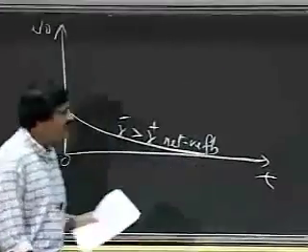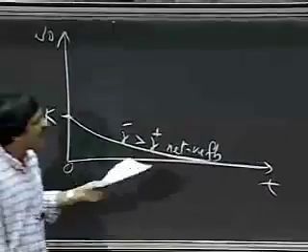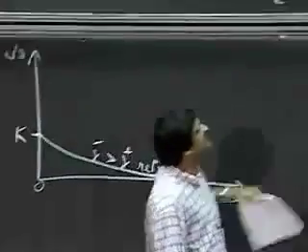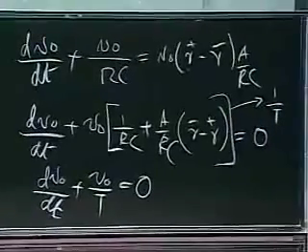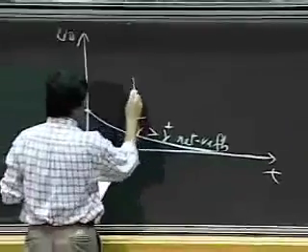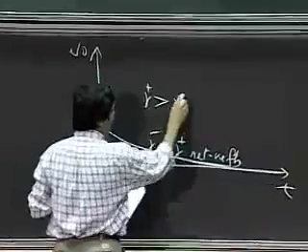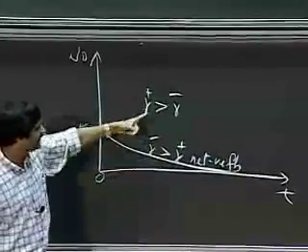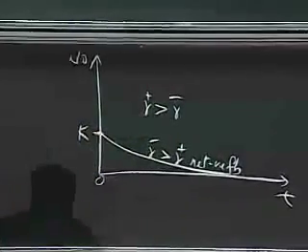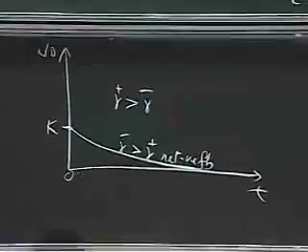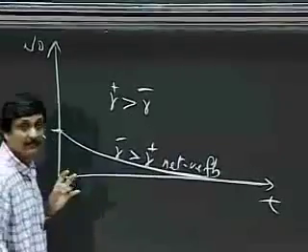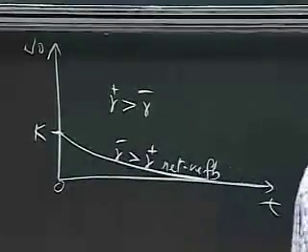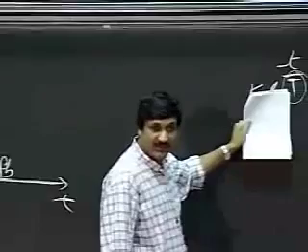So let's take a look at another situation. What happens when the opposite is true? What happens when gamma minus is less than gamma plus? When I feed back more, what happens when I do this? When gamma plus is greater than gamma minus. The opposite is true. This means that I'm feeding back more to the positive input. A bigger proportion goes to the positive than the negative. What happens then? Then capital T becomes negative.